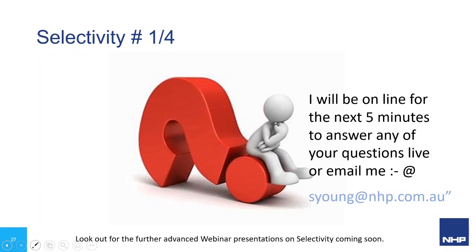Great, thanks for that. We have one from Ben here. He has heard some feedback that type B miniature circuit breakers trip easily and are bound to have more nuisance tripping than when people would use a C-type miniature circuit breaker instead. He's just asked for an opinion and some general comments on that. So the B-type nuisance tripping more frequently than the C-type miniature circuit breaker: absolutely correct. That's because of its characteristic of an instantaneous trip point that averages around about 4 times its nominal rating, whereas a C curve is about 7.5 average on its nominal rating.